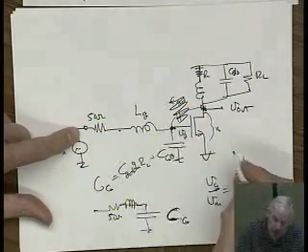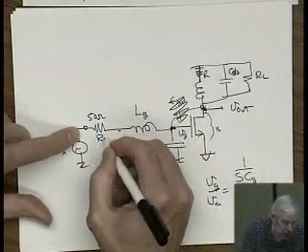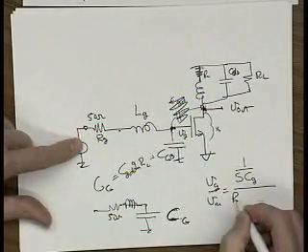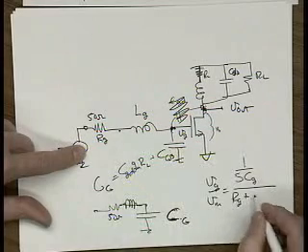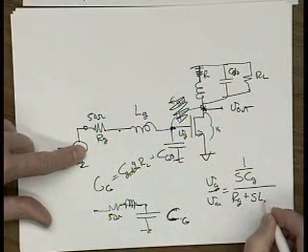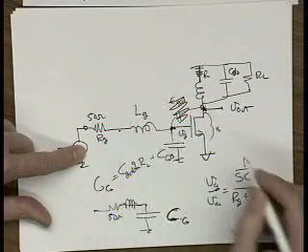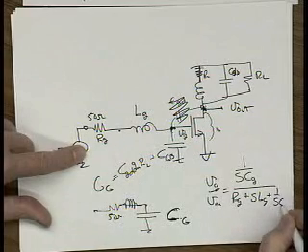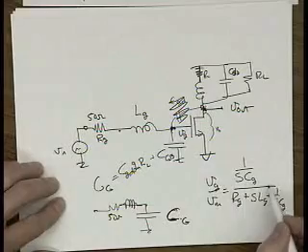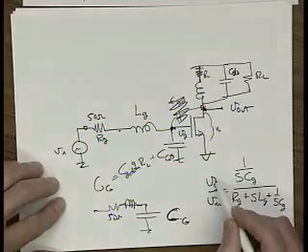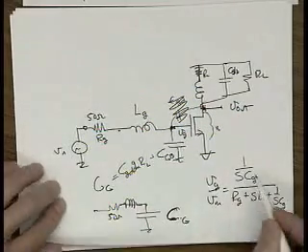And we have a voltage divider. Let's call this RG here instead of 50 ohms. Just make it RG plus the drop across this SLG, which is the impedance of this LG, plus 1 over SCG. Okay, so this is the voltage divider. So this is the voltage I see at the gate.